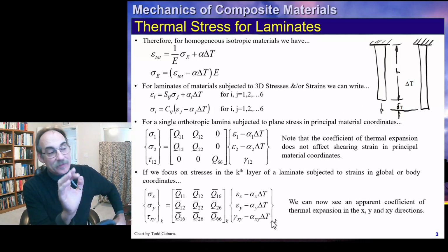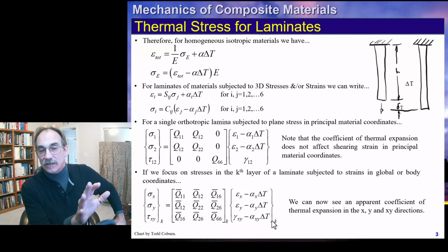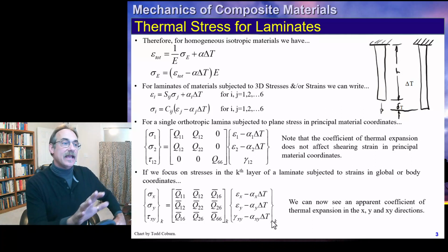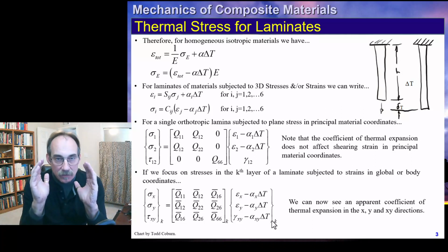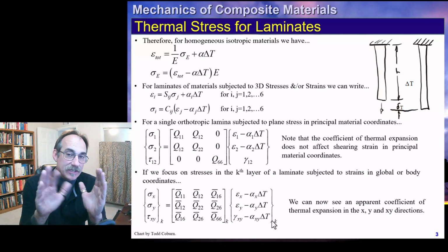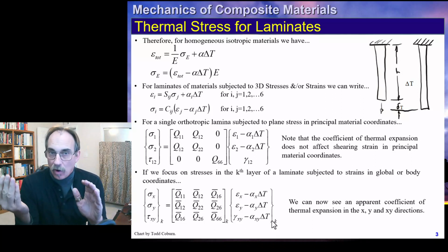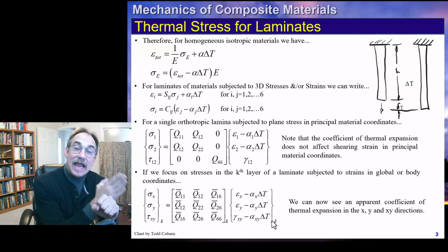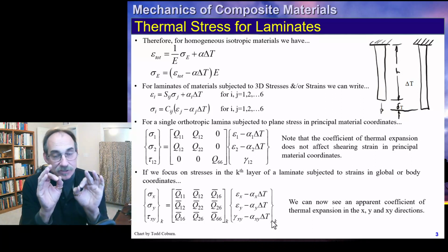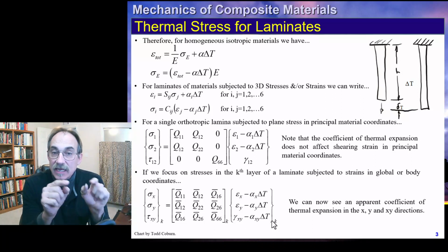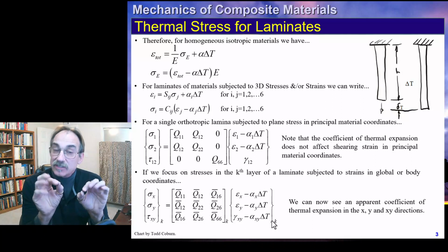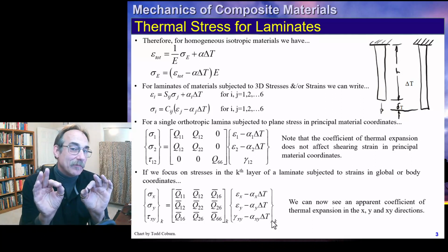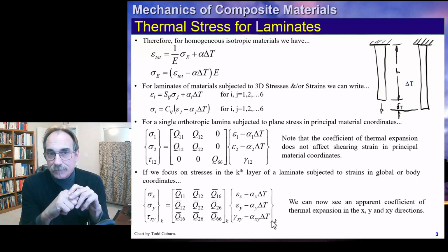in the ply. This is the key to this analysis, and this is how we can take total measured strains, remove the thermal part of it, pre-multiply by the Q-bar matrix, and get the stresses in the ply in body coordinates. Now stay tuned, because this is the key to how we're going to do this analysis, or actually it's one key or one building block for our approach.